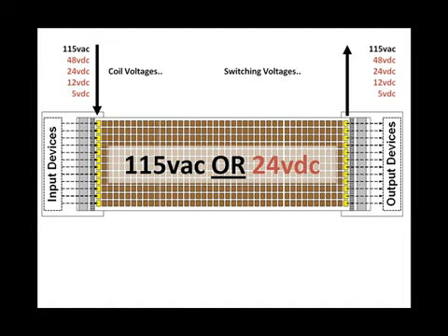I mentioned earlier in this presentation that we would replace these relay coils with computer memory as the first step in our transition from relays to a programmable controller. To make this illustration a more simple transition, let's rotate the relay panel to more closely resemble an array of relays 16 coils wide, and increase the quantity of relays to match a typical computer memory size, in this case 8K of RAM, random access memory.